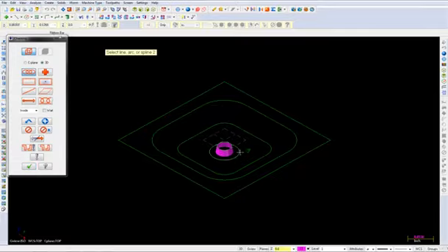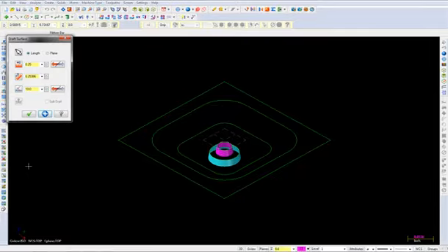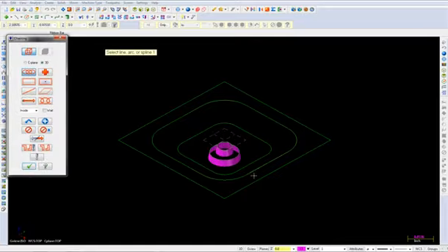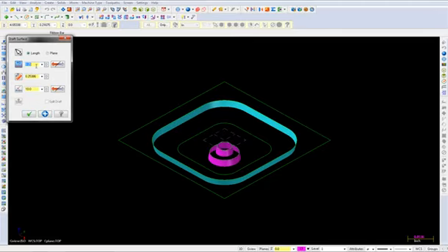Select the Apply button and chain this arc. Choose the OK button. Ensure that the length is set to 0.25 and the angle is set to 10 degrees and that it's in the downwards direction. Select the Apply button once more. Select this outer rectangle here, choose the OK button. Change the length to 0.375. Ensure that the surface is created downwards with a 10-degree angle as well.